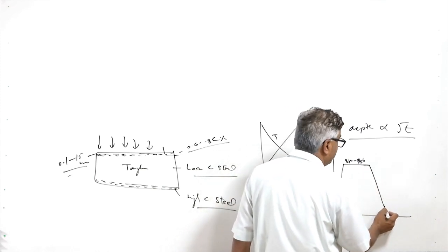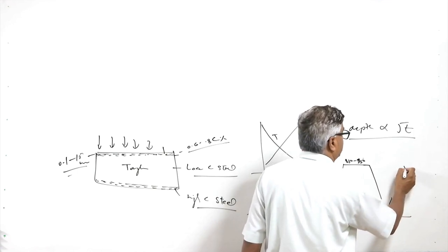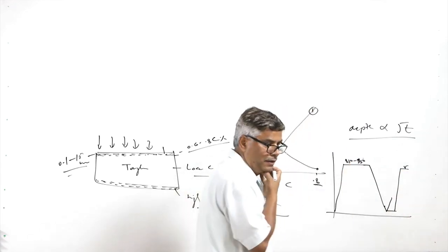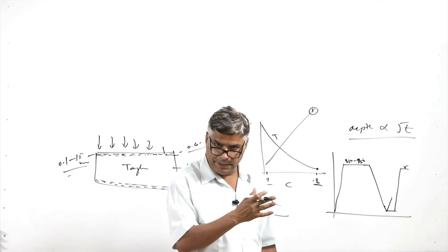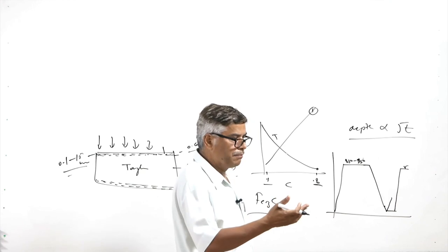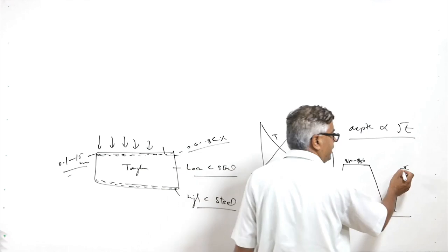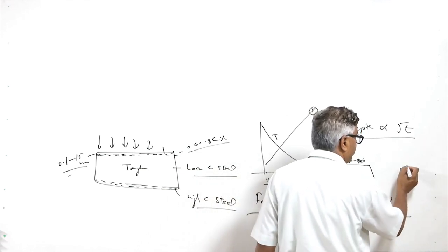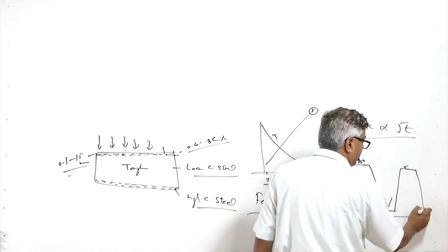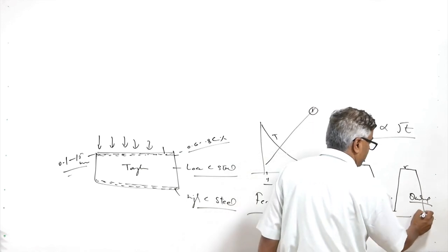After cooling, again it is heated to the austenitic state, so that it forms the austenite. For the carbon content, this will be leading at 0.8%, it will be leading to the eutectoid composition of the steel, wherein upper eutectoid temperature is 730 degrees centigrade. So heating up to say 800 degrees centigrade will be leading to the formation of the gamma, that is austenite. So once the homogeneous austenite is formed, it will be quenched hard. So quenching will be leading to the formation of the martensite.